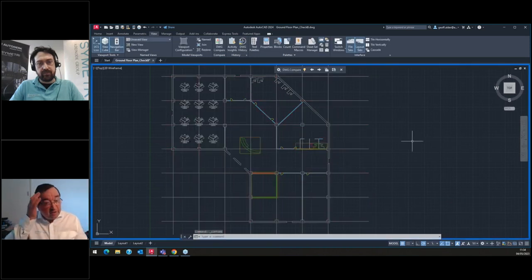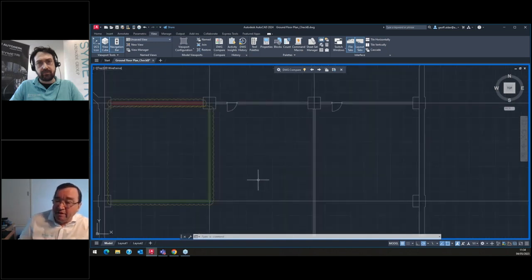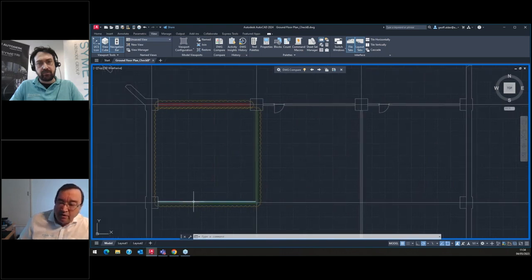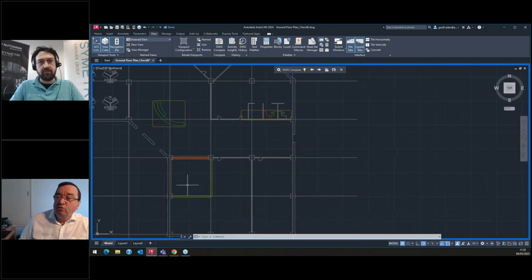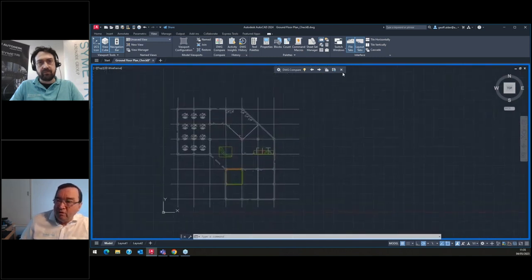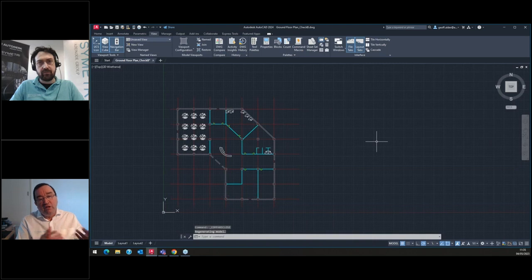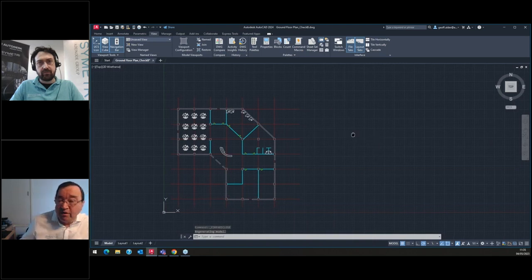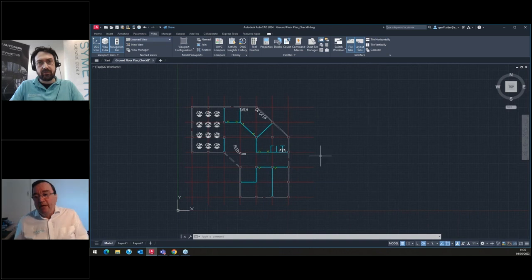And you can see that this particular drawing compare is flagging up a few places here, that on this occasion, the interior wall has been changed from this one, which was the original one, to now being put around here. So the drawing compare is actually quite a powerful tool in association with things like the traces and this type of thing. So like I said, the collaboration, the change is very apparent here, which is really useful. Now, those two features I quite like in AutoCAD, in our way forward.